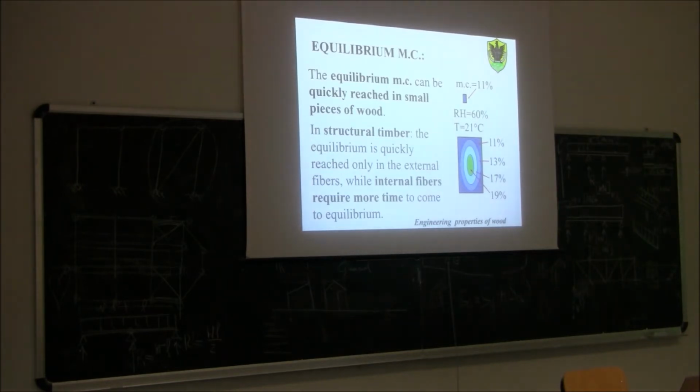Equilibrium moisture content is, in the end, also a matter of time, but if we keep the environmental condition constant over time, it will perhaps take months, but in the end, all the fiber will tend to go to this value of 11%.